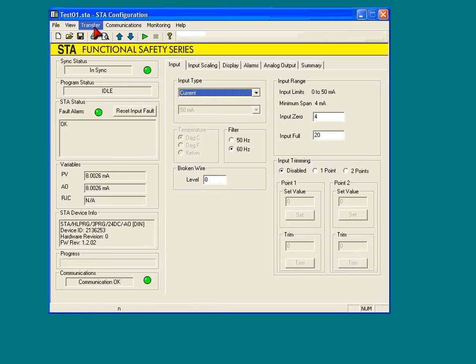Okay. Then communications, COM 1, 2, 3. Right now I am using COM 3 on my computer, and I also have to tell the software that it should be listening to COM 3. So they have to agree with one another that they're both set to COM 3. So if you're using COM 1 in your computer, you'll have to set COM 1 here as well. Monitoring, this is the same as the VCR buttons. You can say monitor or stop, the red stop button there.